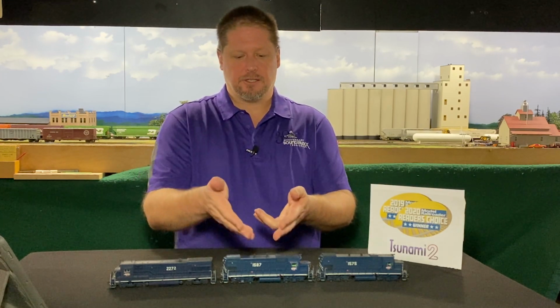Now the second unit here, 1587, hears that command and says, yes, I'm part of consist 20. So move forward, speed step 10, yes. Am I supposed to respond to F0? No, no headlight. Am I supposed to respond to F1? Nope, no bell. Am I supposed to respond to F4? Again, let's assume it has dynamic brakes. Yes, I'm supposed to respond to dynamic brakes.